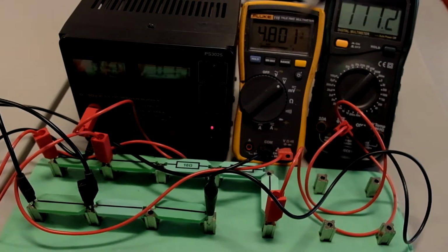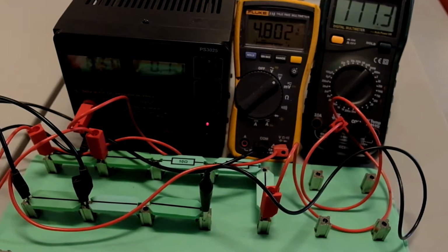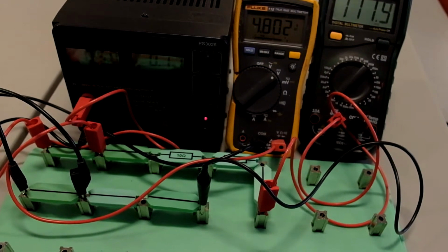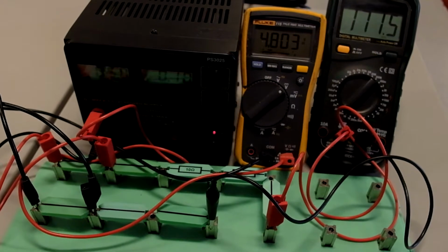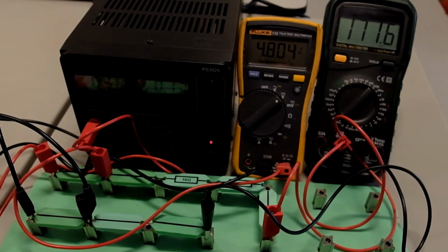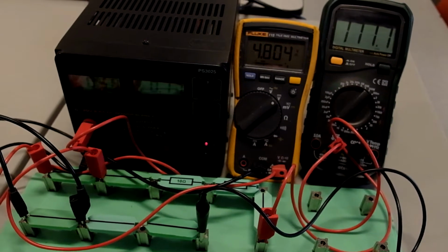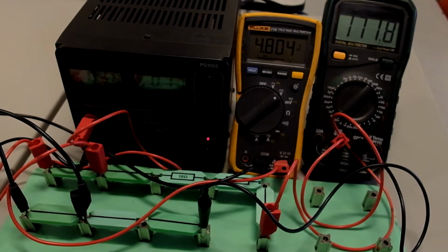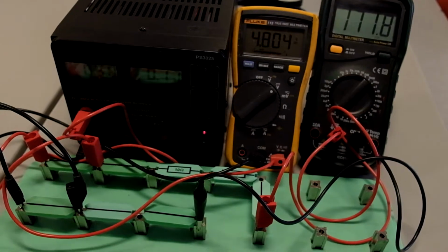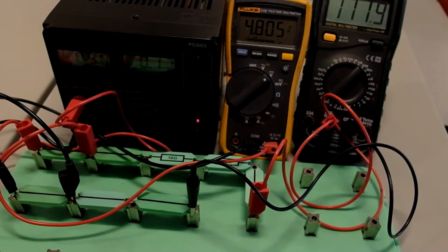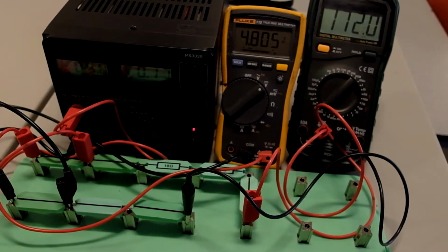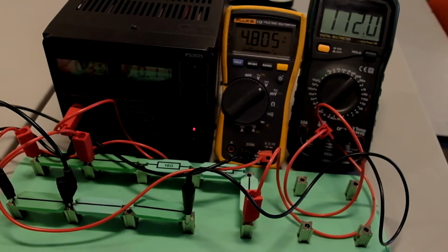So why do we have less voltage now on the voltmeter? We have less voltage now on the voltmeter, which is across the DC power supply, because the DC power supply has effective internal resistance. So it's not necessarily one single resistor, there's electronics in there. And we want to determine what an external circuit will see as an effective internal resistance.